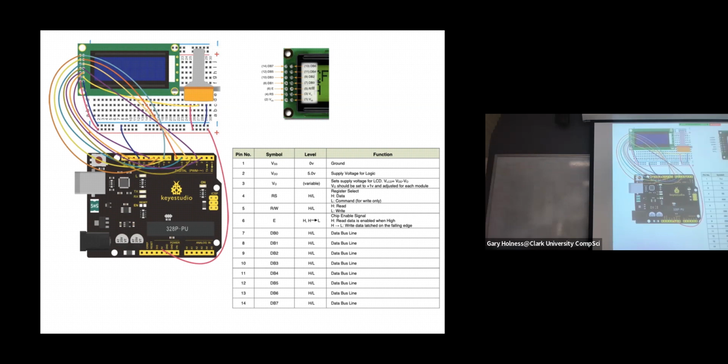Now, there's really no difference which digital I/O pin you use on the board to feed one of the signal or control lines for the device, outside of it looks nicer, right? You don't want to have wires kind of crossing and woven like pasta or something like that, because that'll make it physically harder to trace where things are, right? But it's entirely up to you which digital I/O lines on the board you use to drive the various signal and control lines on the device.